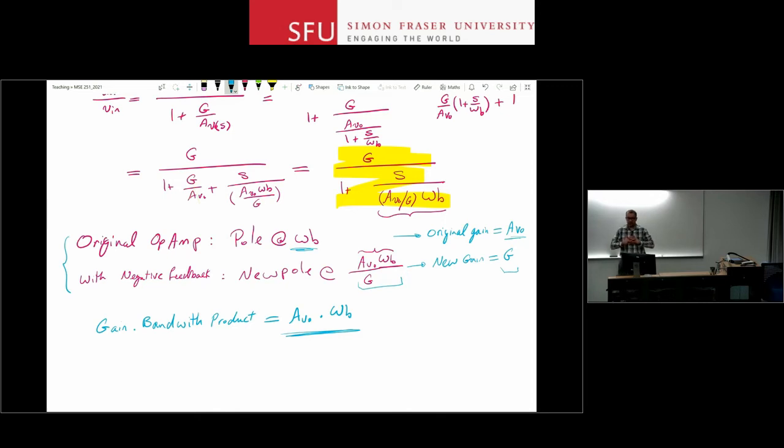For all of these op-amp circuits, that corner frequency moves with your gain. Increase your gain, the corner frequency goes lower. Decrease your gain, let's say 1 plus R2 over R1, that's the gain I'm talking about. Lower that gain, your bandwidth increases. The product of the gain that you get out of that op-amp and its bandwidth, the frequency band that you can amplify a signal, is constant.